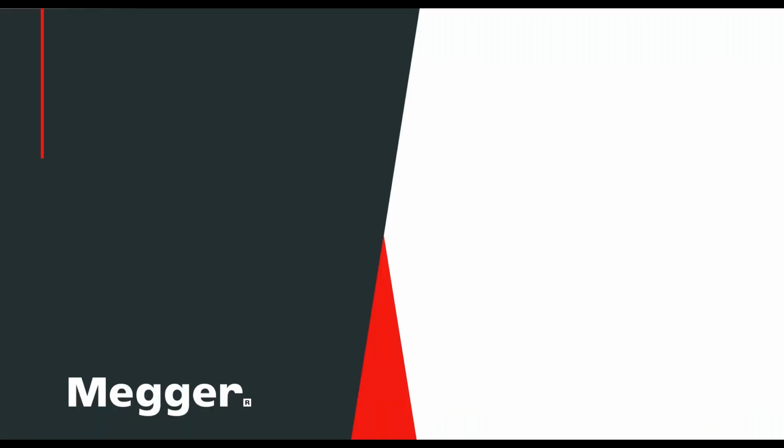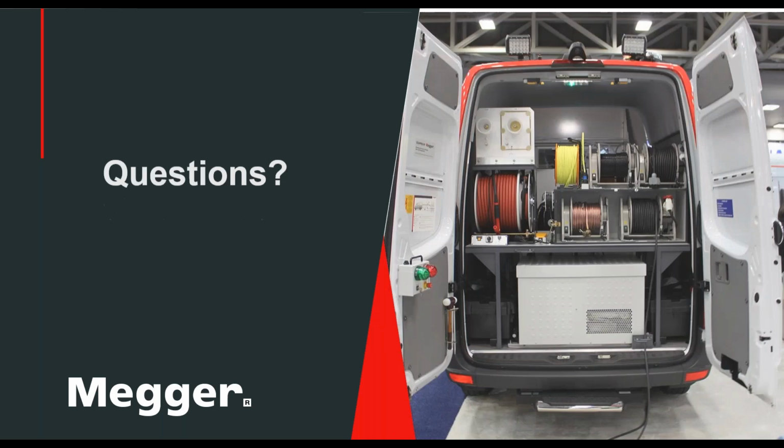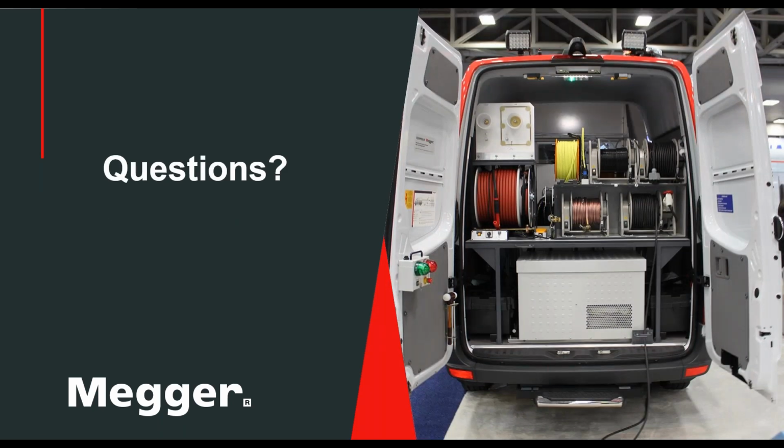The first one's going to be for Sergio. Sergio, can SmartThumps be used for high voltage cables from the 69 kV to 230 kV range? My answer to this was that it depends on the breakdown voltage of your particular fault, and if the breakdown is higher than the SmartThump range, a larger unit will be needed.